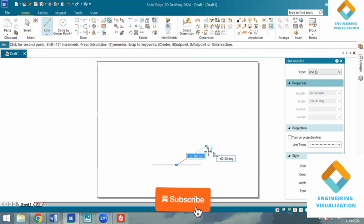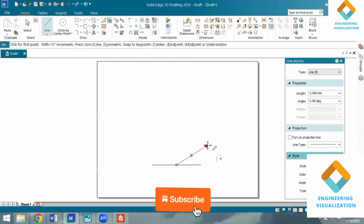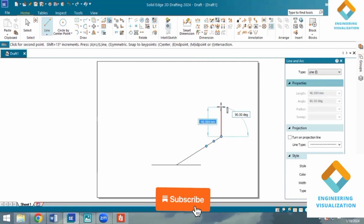Okay, first I'll be constructing a rectangular block. So here the rectangle block having base sides 30 mm, 30 degree and vertical edge 60 mm, angle is 90 degree. Again length is 30, angle is minus 150, and then vertically downward is joined with a length of 60 mm.